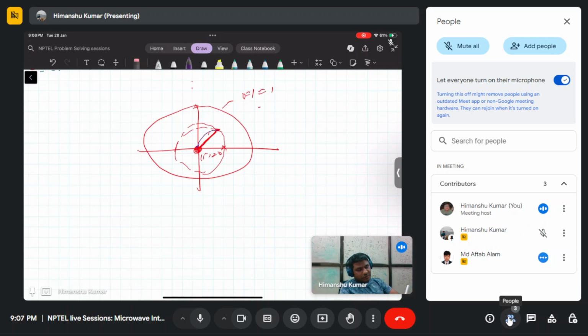Any point you need to transfer to the center of the Smith chart to match the impedance. It's where gamma real and gamma imaginary equal 0, the center of the constant gamma circles, the center of the Smith chart.